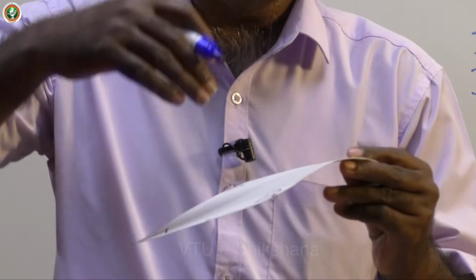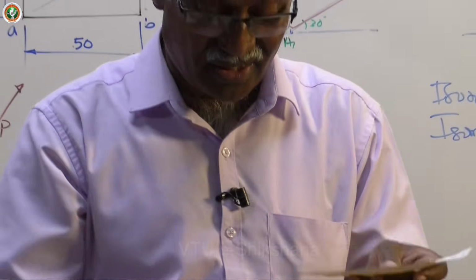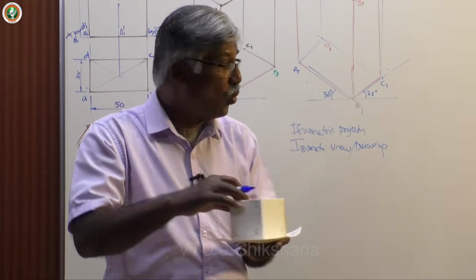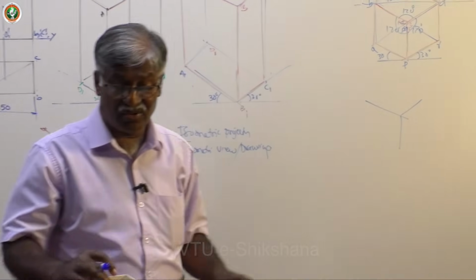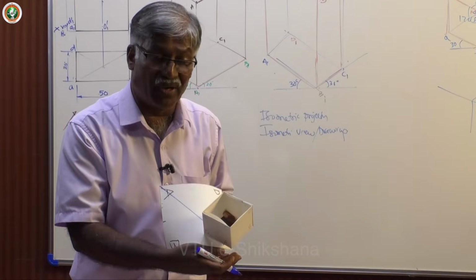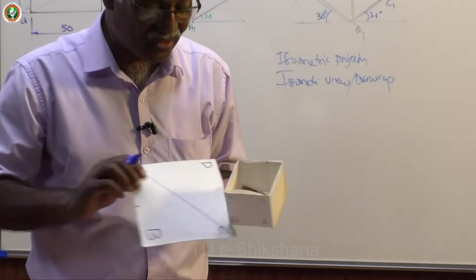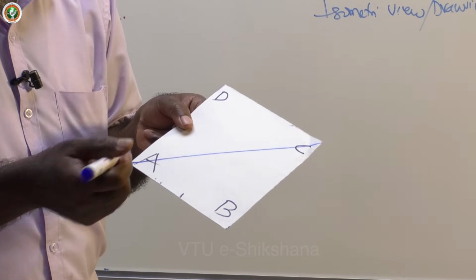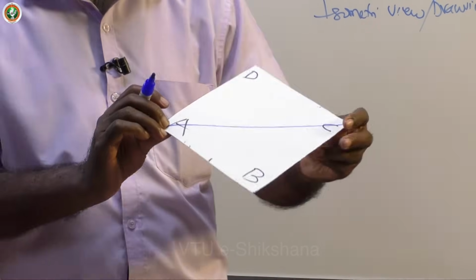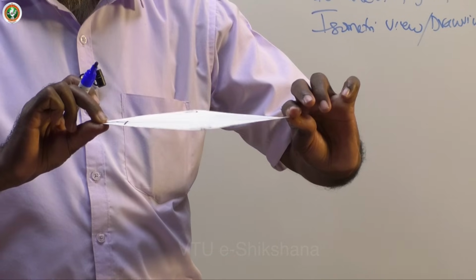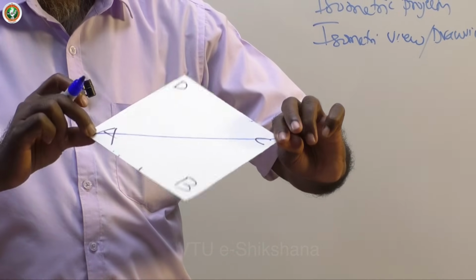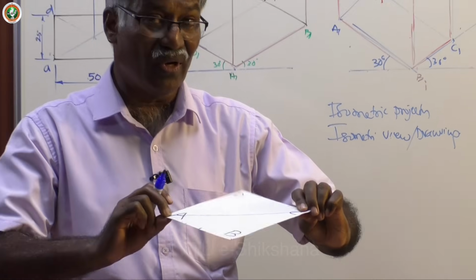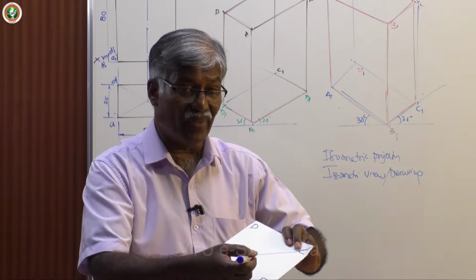Okay, when the top face is parallel to HP, when it is resting on HP like this. Now, when you get this particular position, that is, the solid diagonal is parallel to VP and perpendicular to HP, it will be inclined at some angle, so that this figure is going to give a rhombus. And again you observe AC in the first position and second position. AC distance never changes. About AC only it is rotating and gives you the rhombus.